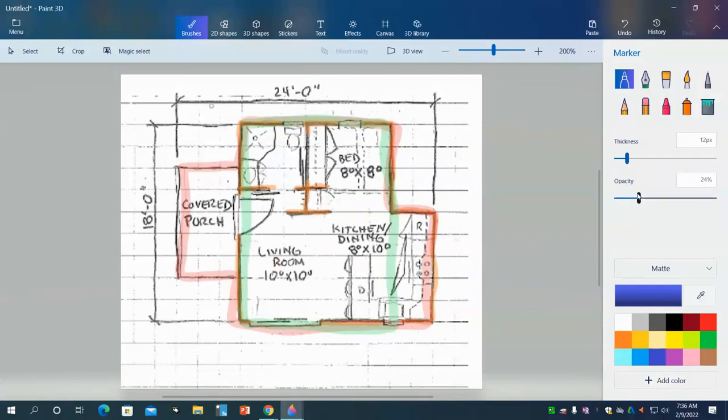Now, when I do this ridge, it has to be exactly in the center. So what some people would try to do is put a ridge right down here and tell me the water's going to run off the building here. That won't work because these walls would end up being much taller than everything else. So that will not work.